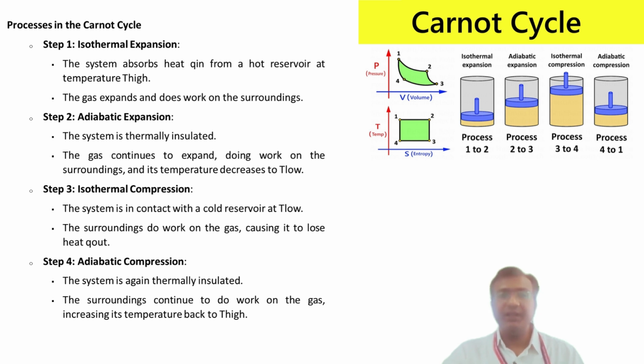Next is the adiabatic expansion. Now here, after the isothermal expansion, the system is thermally insulated, meaning no heat can enter or leave the system. So the gas continues to expand during this process and does more work on the surroundings. Since there is no heat exchange, the expansion causes the temperature of the gas to decrease until it reaches the temperature of the cold reservoir.